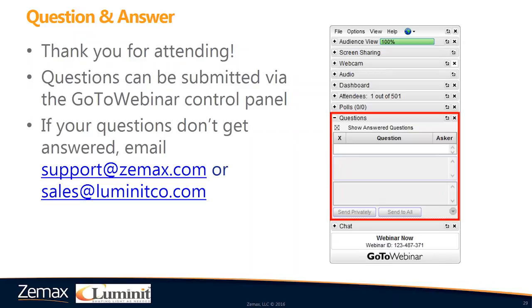Do the Luminit models work on curved surfaces and also in the presence of TIR? Okay, as far as curved surfaces go, this model will not work properly on it. Basically, they'll treat it as if the surface was normalized to the Z direction. Okay, so the normal pointing in the Z direction. So it won't even consider the surface as if it was curved. It would think it's a flat surface and go straight through. The light rays would go straight through.